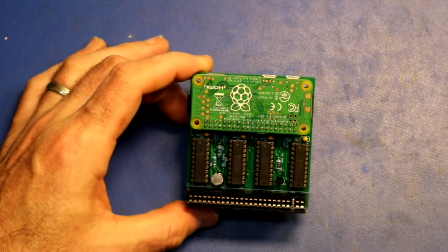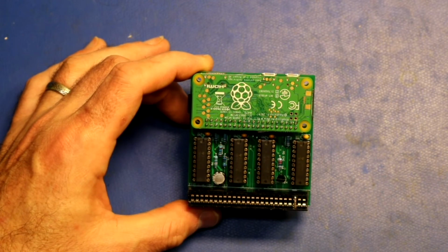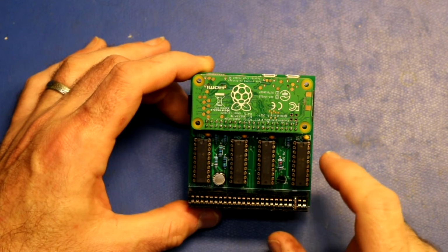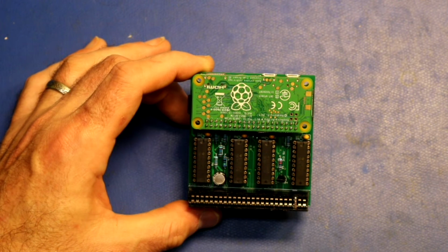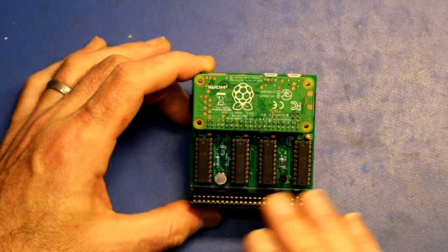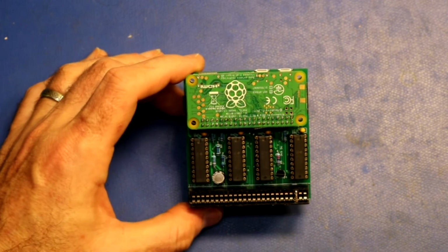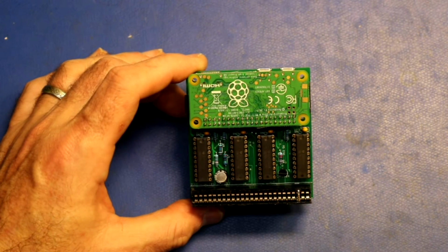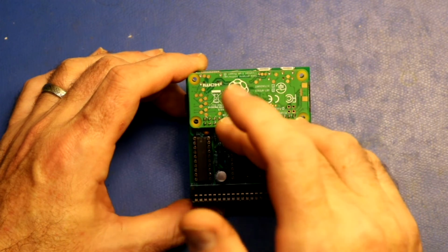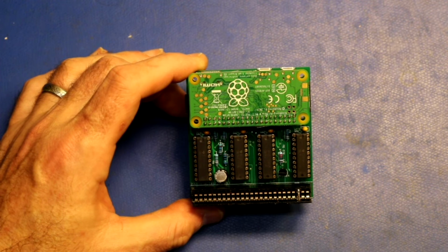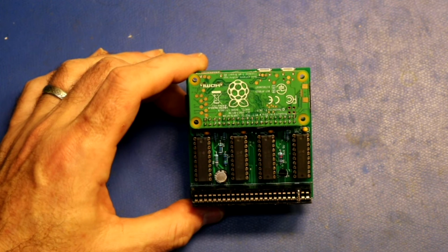And what it does is allow you, by using the bus hold line on the connector, to seize control of all of the peripherals and the memory from the CPU. So you can put the CPU into a bus hold state. It will acknowledge that with a bus ACK, and then you can go around and do stuff with memory. So I've got some transceivers and some latches here that the Raspberry Pi will use to set the address and the data, and it can either read memory or write memory while the CPU is in that hold state. And you can use that to do all kinds of interesting tricks.